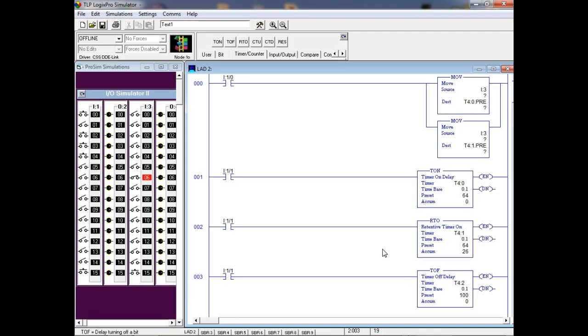Normally we would say, okay, I want to run a motor for 15 seconds, and then I want to stop it for 10 seconds, and then I want to run it reverse 18 seconds. Well, what we would do is we would start it with our first timer, and then when it finished, it would go to the next one and keep up with the stop time, and then it would go to the next one and keep up with the reverse time, and then we might repeat it. It depends. Normally, that's what we use multiple timers for, right?